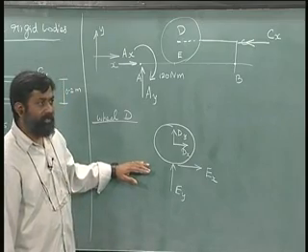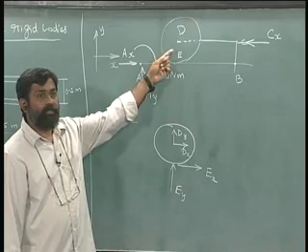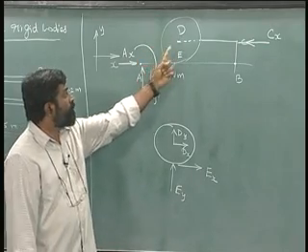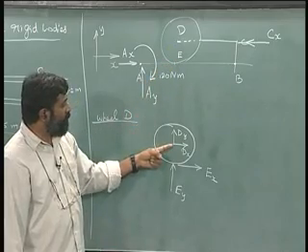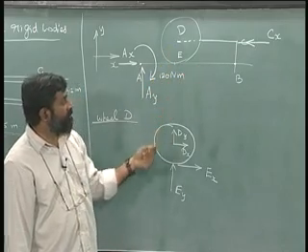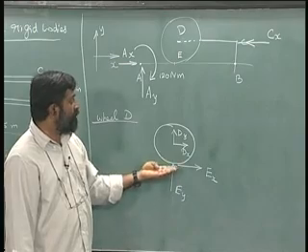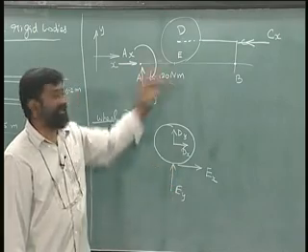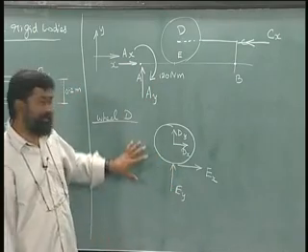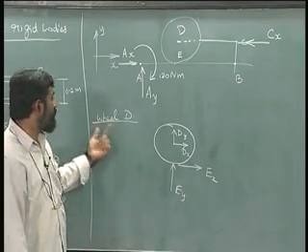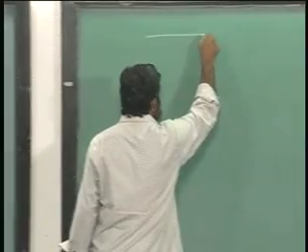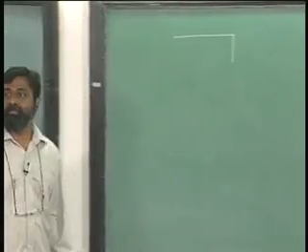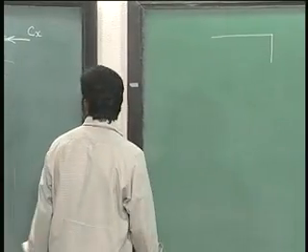Have we missed out anything else? The mass of this particular wheel is negligible, which means there are only 2 points that I have to consider: one point of restraint coming from BCD and the other one due to resting at E. So this is complete as far as wheel D is concerned. Let us seek to draw the other two free bodies. I am going to use line diagrams in order to make it simple.